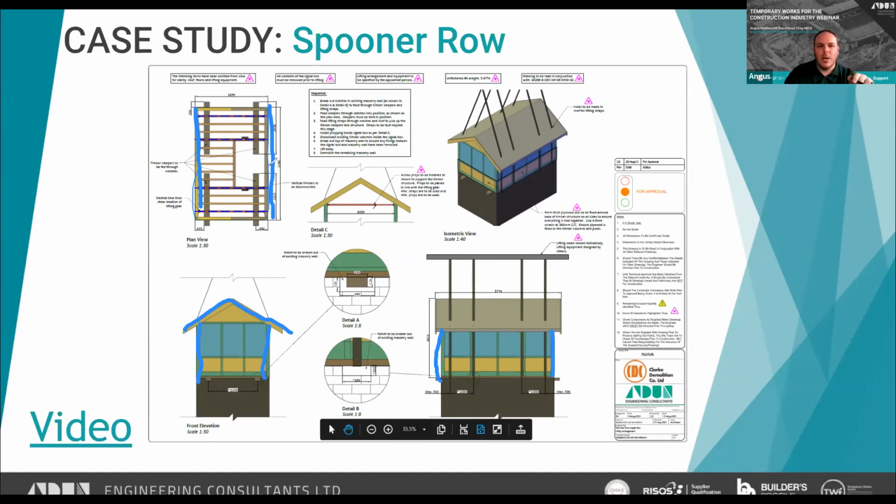And they were quite robustly proportioned because of the loadings that were in there from the original signal levers, I think, because they were quite chunky even by the standards of what you'd expect from the age when it was constructed. They were chunky. And then in addition to that, you had the strops that we detailed come up and around, and they pick up directly underneath the outer wall here, here, here, and here. Same on the other side.